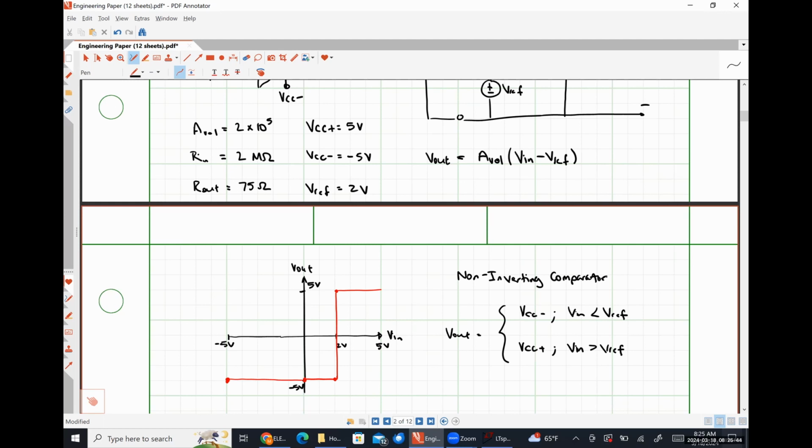And then we could do something similar for the current signal, and then the difference between those two timestamps tells us what the difference in phase angle is between them, which in turn gives us our power factor, right? So zero crossing circuits use comparators all the time. They can also be parts of analog to digital converters, and we're going to design one of those here in just a couple of minutes.